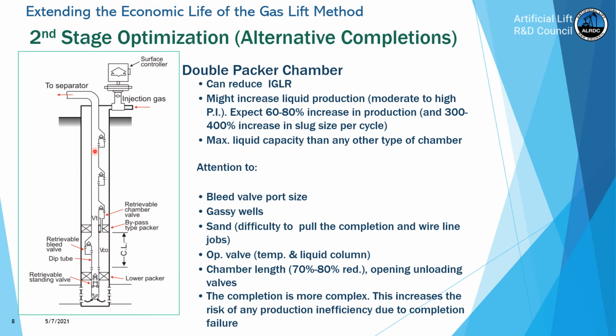You should make sure that the instantaneous gas flow rate through this pilot valve is high enough so that the liquid, even though it's very large, will reach a velocity in which you minimize the fallback losses.